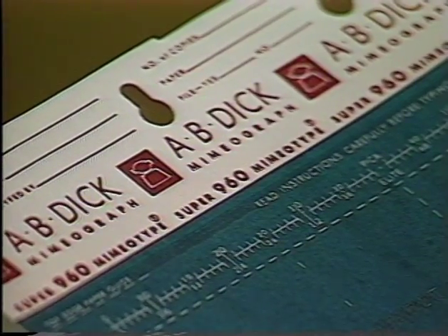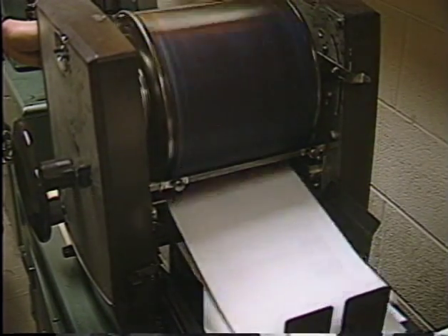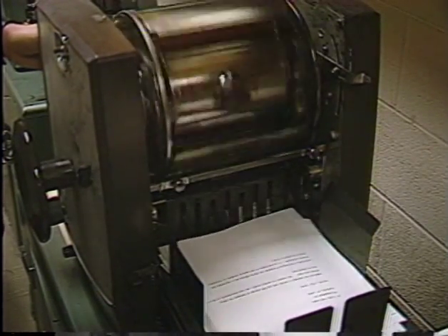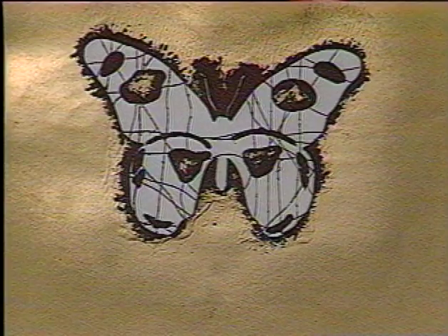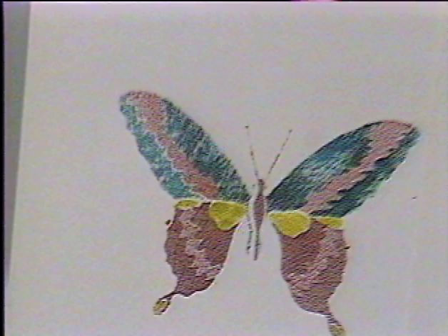Mimeograph is an example of stencil printing. In this method, a waxy coating on a mimeograph stencil is removed to expose a fibrous structure underneath. The stencil is mounted on a saturated ink pad where ink passes through the fibers onto an absorbent paper when pressure is applied. Stencil printing was practiced by the ancient Chinese, who used human hair to hold the parts of their stencil together. They produced some excellent reproductions using this intricate, time-consuming procedure.